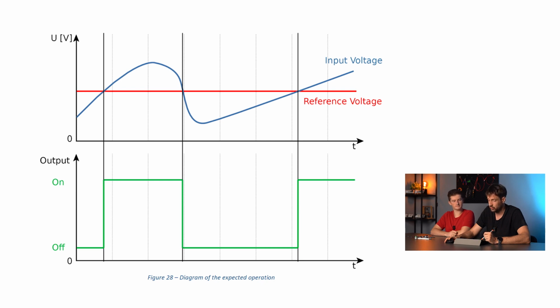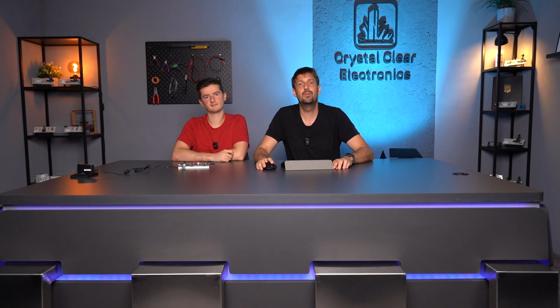The figure shows how the levels of the input and the reference voltage affect the LED brightness. The battery testing circuit from the previous section has some faults, due to the fact that the voltage on the Zener diodes will change slightly if the current changes.